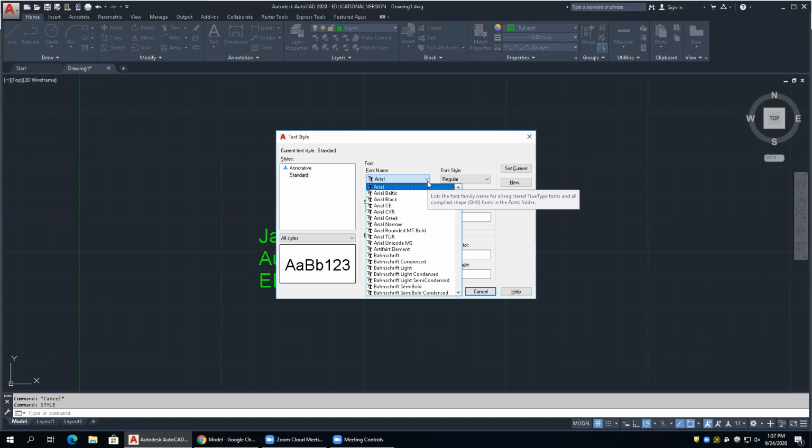If you scroll down through that list, you will see another little symbol pop up. Looks like that's one bold, SHX. That's an AutoCAD proprietary font. That's called a shape file. S-H-A-P-E, shape file. So at one time, AutoCAD could not read true type fonts. So they had their own fonts, okay? So now they have both, okay? We can use both.